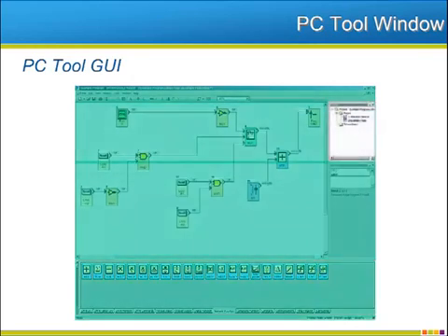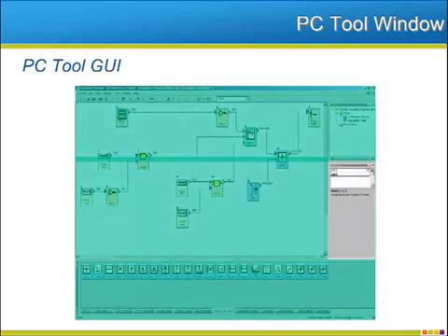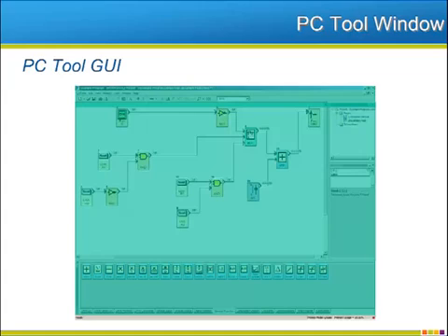The Project Navigator section is where the user can add a new page or select different pages within the project. The Properties window shows the information associated with the selected function block on the program page. At the very bottom, you will see the status bar. The user can immediately tell if the PC is online or offline, whether DrivesWorksEZ is monitoring or not, and the percentage of available connections used. So the number of connections used will account for a different percentage depending on which version of DrivesWorksEZ is installed.